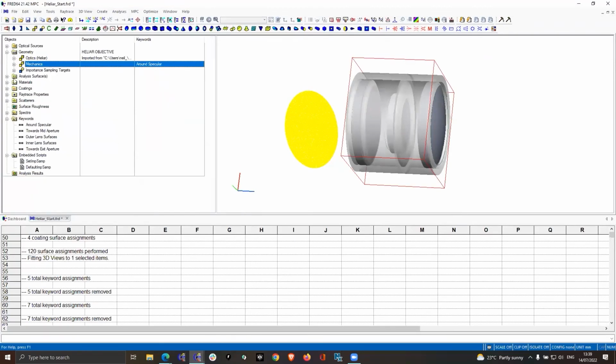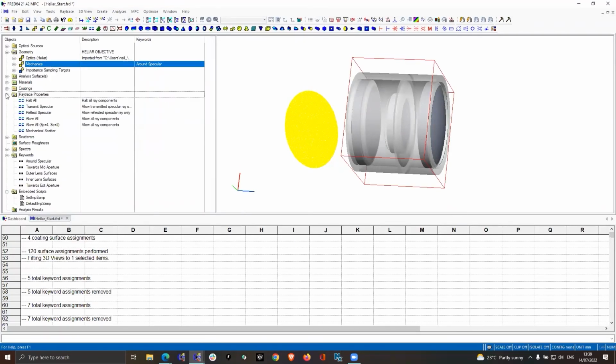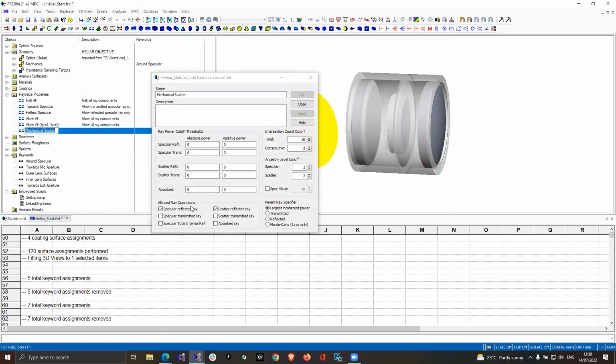So once we've allowed a specular reflected ray, we have to then decide what power that ray has. And it's the coatings that tell us how much power that ray has. So in this very simple demo here, we said we had a 100% reflective coating, which essentially means that the specular ray has all the power that it should have after the energy for scattering has been taken out, but there's no further absorption. Hopefully that answers that question.